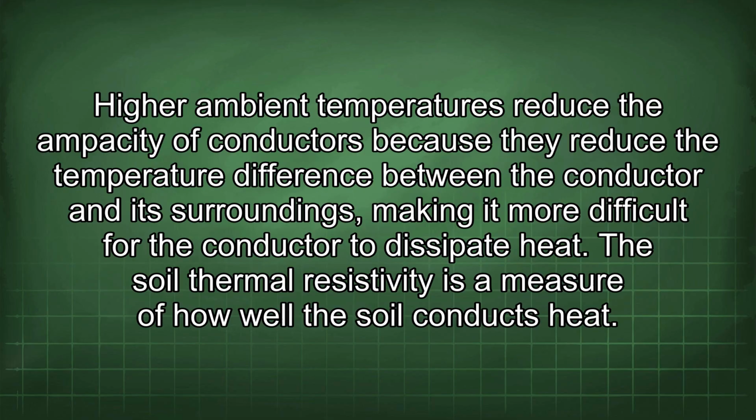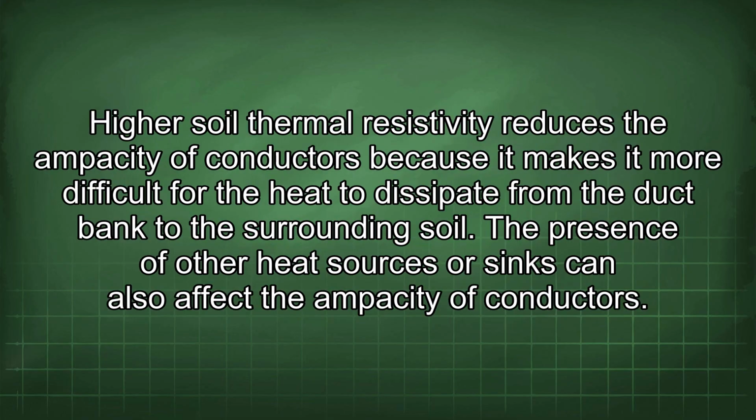Higher ambient temperatures reduce the ampacity of conductors because they reduce the temperature difference between the conductor and its surroundings, making it more difficult for the conductor to dissipate heat. The soil thermal resistivity is a measure of how well the soil conducts heat. Higher soil thermal resistivity reduces the ampacity of conductors because it makes it more difficult for the heat to dissipate from the duct bank to the surrounding soil.